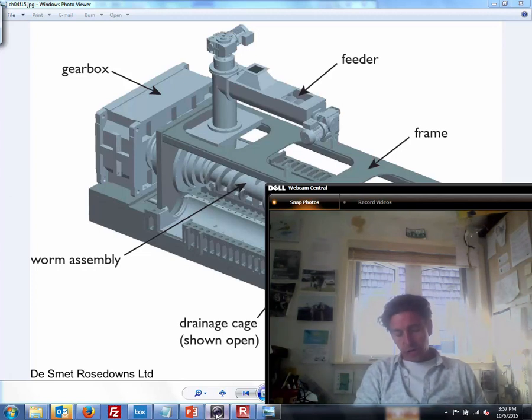Another one, it says variations on the basic process include solvolysis, the use of organic solvents. So there's more chemistry rather than just pure thermal, at 200 to 300 C to dissolve the solids into an oil-like product, and fast pyrolysis requiring temperatures of 500 to 1300 and high pressures. It says fast pyrolysis with the capture of the volatiles is used in the production of commercial charcoal. But as of this writing, pyrolysis processes for liquid fuel production are mostly at the pilot or demonstration stage.